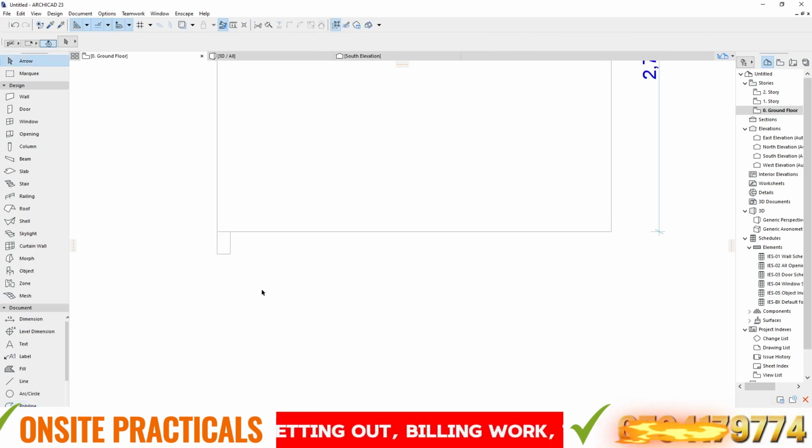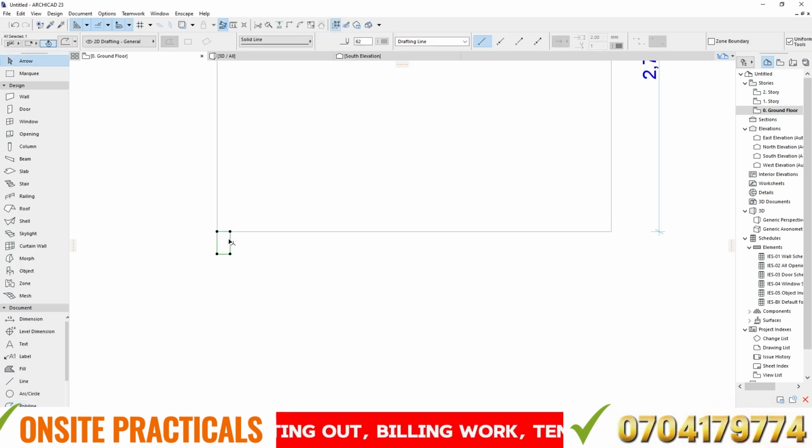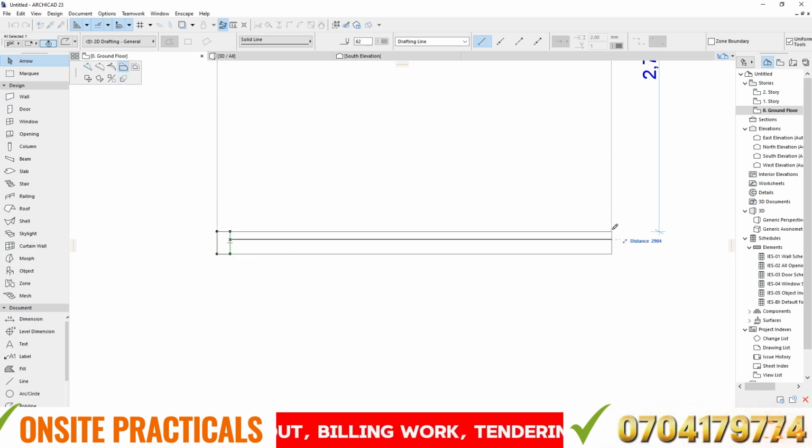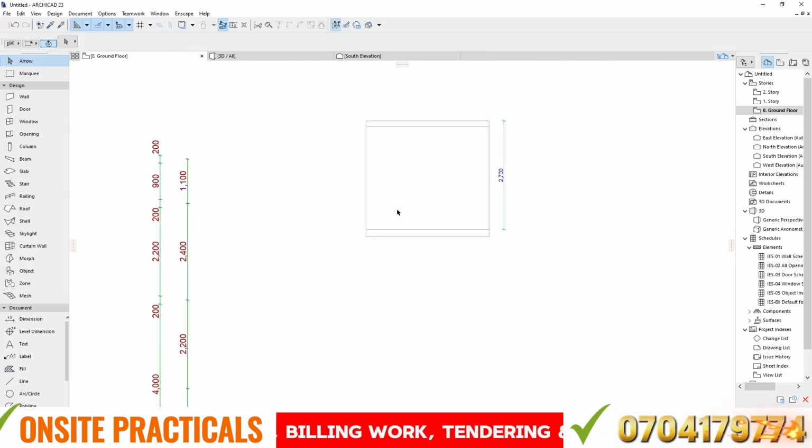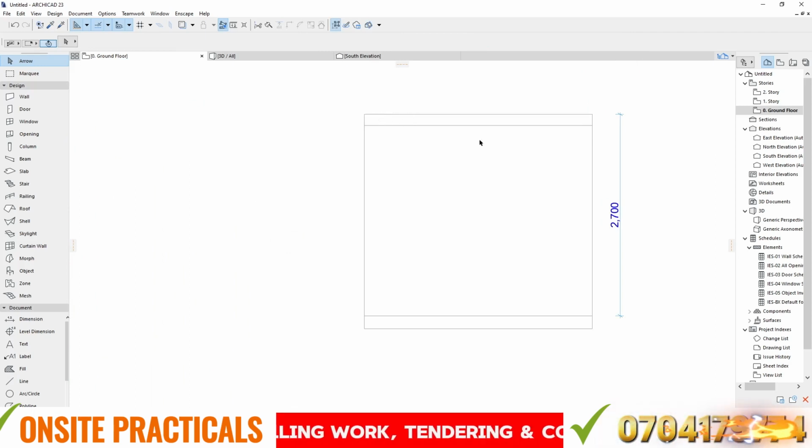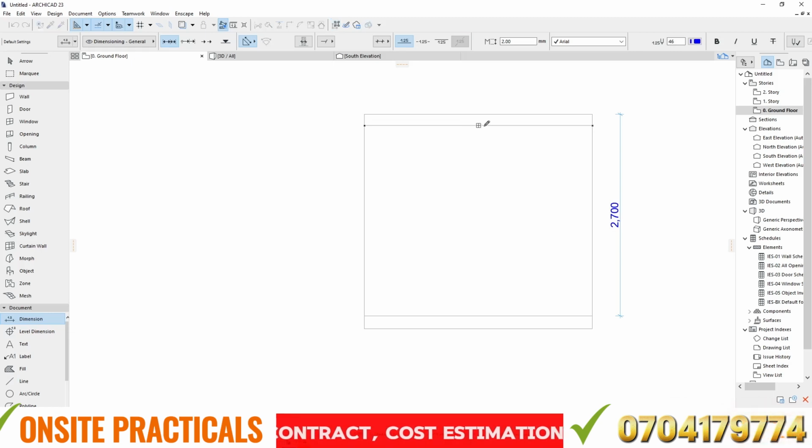So that's basically what exactly those reference lines will mean. So in our case here, for example, you're going to have it there. So that now when I want to know the height, the floor to floor height will be actually this, so that then the bottom of my slab here will actually be my ceiling. So now if I take the ceiling height, it will be the floor to floor height minus the slab height.